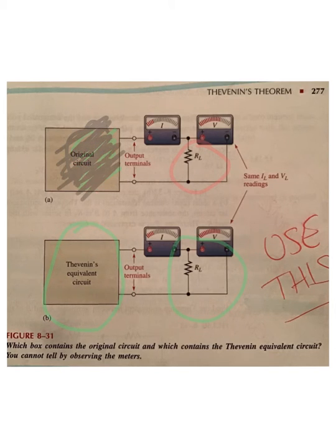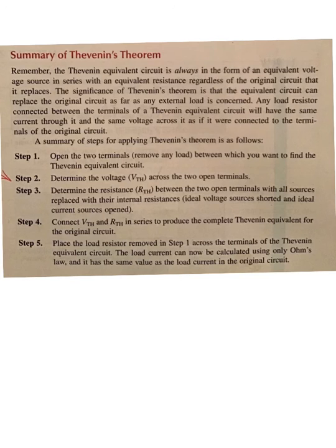So if we can take the complicated circuit in black up at the top and characterize exactly what voltage is going to be out here at the terminal and how much current is going to flow into this load that's circled in red, then we could build a simpler circuit called the Thevenin circuit, almost like a surrogate circuit that would provide the same current and the same voltage. And this would be useful in solving the circuit for that load if I wanted to change it multiple times.